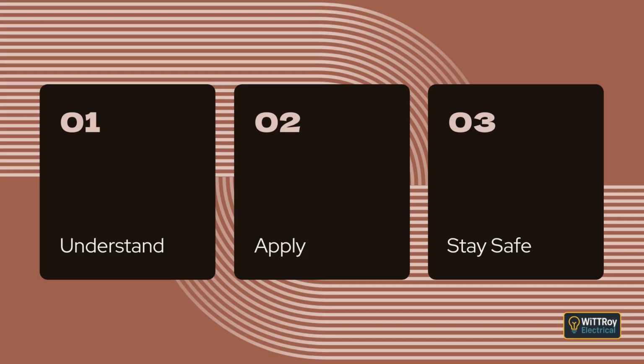Where the wiring is chased into rock, the tape must be laid directly above the cable before concrete is poured. Where underground wiring is installed by directional drilling, tape may be omitted as long as the location of the wiring is permanently recorded so it can be found by anyone digging in the future. If a pipe or conduit is left in place after drilling, using an orange conduit is recommended for clear identification.